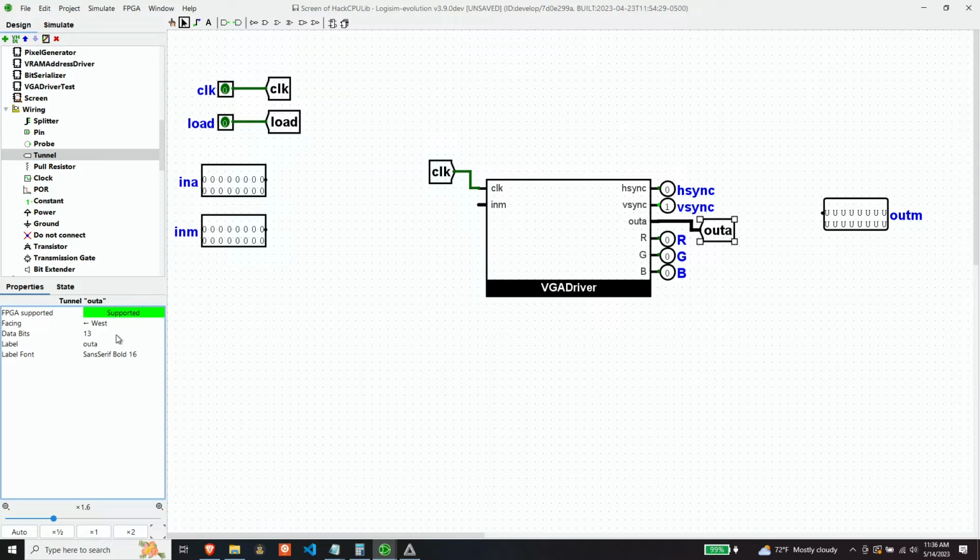If both sources simultaneously need access to RAM, who's going to win? My proposal is that I would rather not block the CPU. And if the VGA driver needs to read a piece of memory, and RAM is busily servicing another request from the CPU, I would rather the VGA driver just get zeros for that particular word.